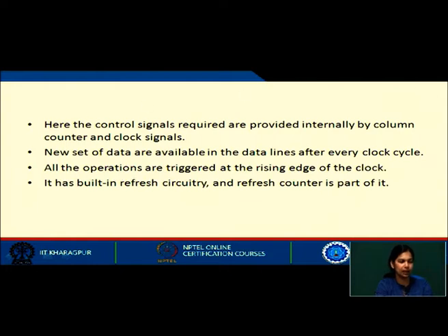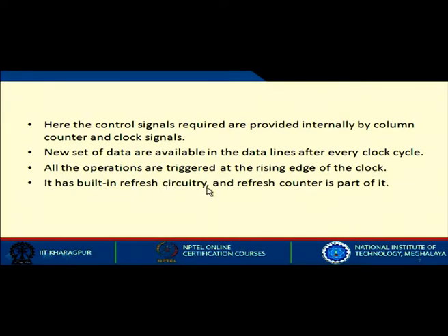So, when SDRAM came, these were the features. All operations are triggered at the rising edge of the clock, but we will see that as the advancement progresses, this has changed, and we could do data transfer both on the rising edge as well as on the falling edge. It also has built-in refresh circuitry, and a refresh counter is part of it. So, there is built-in refresh circuitry that refreshes the different rows of cells of the memory chip.